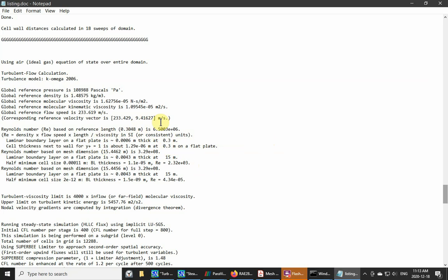So what you can do basically is you can run the simulation for a few seconds, stop it, look at that value, and decide whether you want to increase or decrease the input estimation of what the boundary layer size would be at the mid-chord region. And if you're using a wall function, then you would increase this value somewhat.